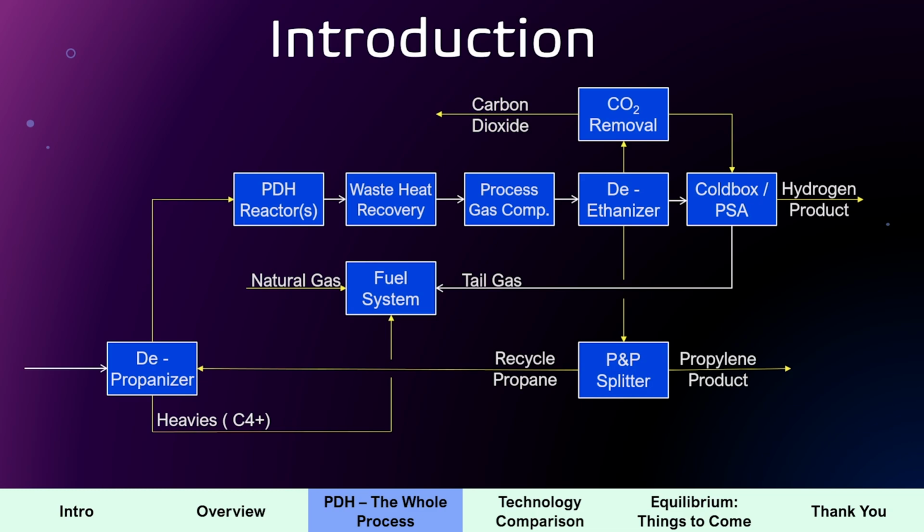So you would imagine that the boiler has to be operating almost as if I am dealing with pure propane, so it's always operating at that temperature. The same applies to the condenser. The condenser is also always going to be operating at the propylene boiling point. Right, so that's where the problem arises in the C3 splitter.